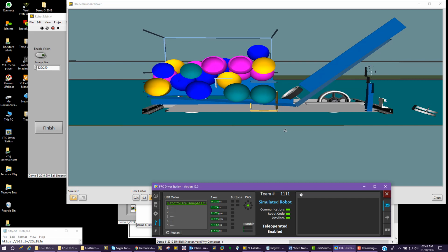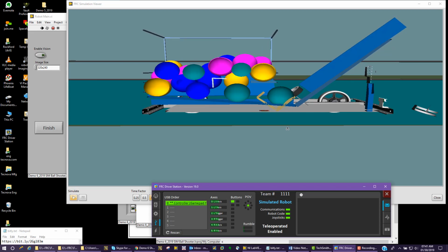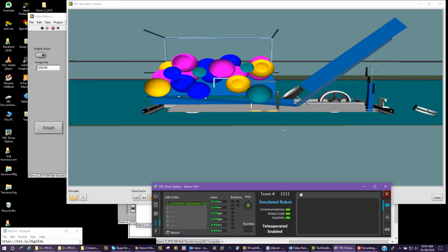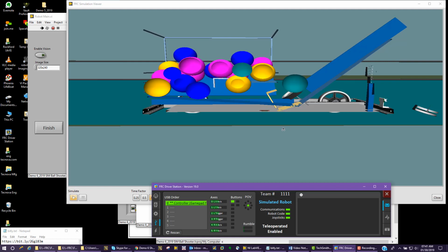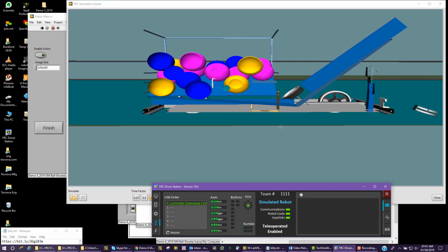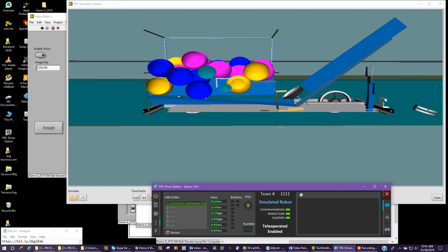So I think what I want to do is put some timing in here so that when I press the button, I get a rising edge, that I shoot it, put it in the ball shooter for a half second, and then release, have the servo come back and stay for at least 1 second before we're allowed to shoot the ball again. We've determined as a team that we only want to shoot the ball every 1.5 seconds. So half a second forward and 1 second back.